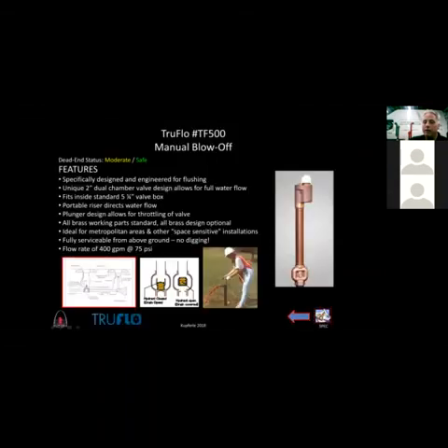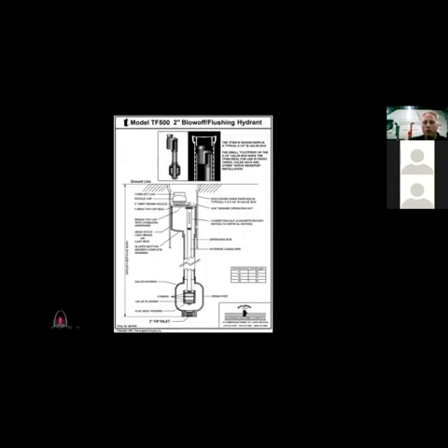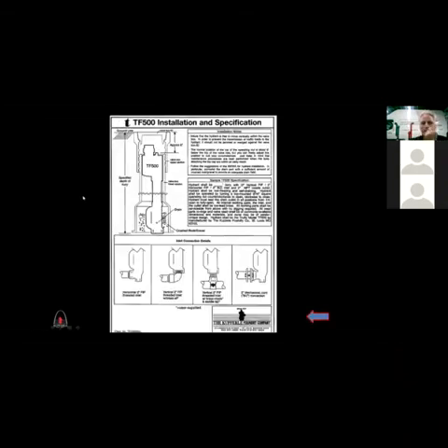So it's going to look like this in the ground. Here's my 5.25 standard valve box. It sits below. Here's the cap that covers up my 2-inch connection. I just thread that off. I put my riser on. Here's my operating nut. I put my wrench on there. I open it up, close it just like a fire hydrant. This has an operating rod and a seat. We'll take a look at that here in a minute. This is what it's going to look like in the ground, underneath the ground here.